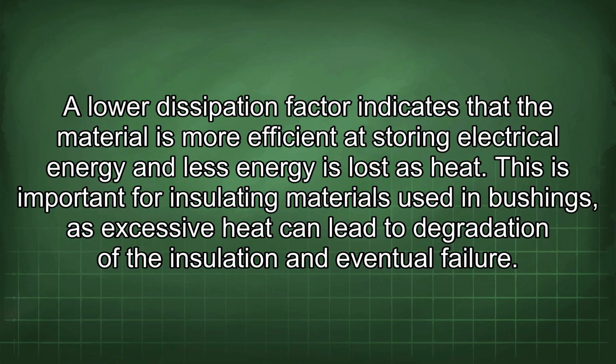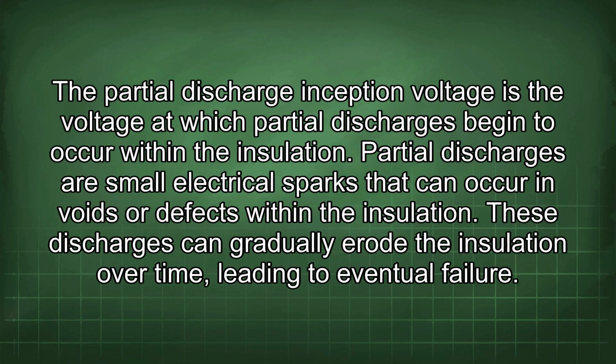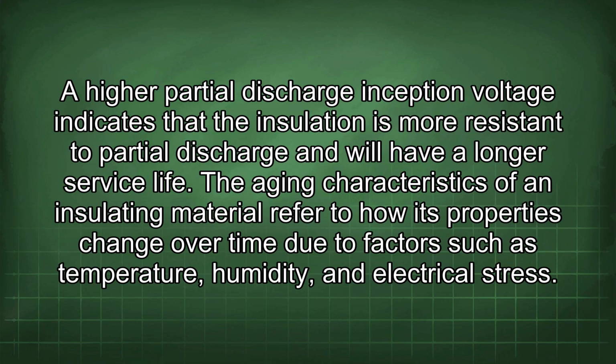insulation and eventual failure. The partial discharge inception voltage is the voltage at which partial discharges begin to occur within the insulation. Partial discharges are small electrical sparks that can occur in voids or defects within the insulation. These discharges can gradually erode the insulation over time, leading to eventual failure. A high partial discharge inception voltage indicates that the insulation is more resistant to partial discharge and will have a